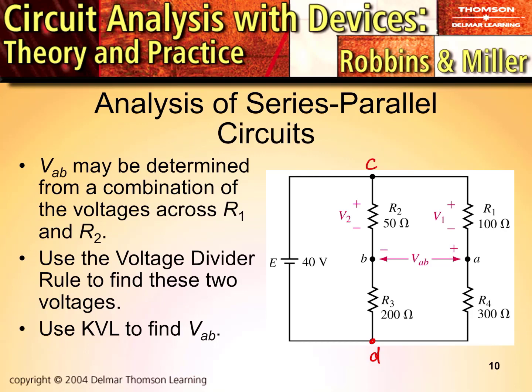So now if we want to move forward to determining our R total, we have to come up with our expression, right? The textbook suggests starting at the farthest branch. The farthest branch is, sorry, had a little bit of a glitch in the presentation there. R1 plus R4 is our series branch for our last branch. We have to pack that up. That's in parallel with R2 plus R3, which has to be packed up as the opposition for that branch, and the two branches are in parallel.